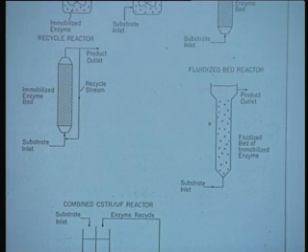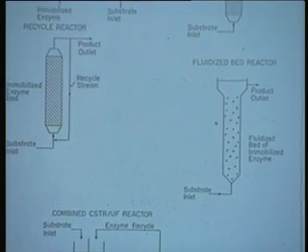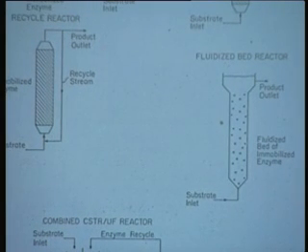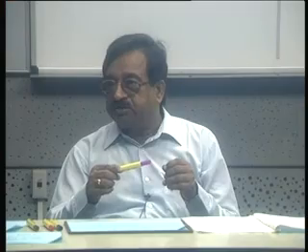It can act as a batch immobilized enzyme reactor, a packed bed with total recycle. The only constraint or assumption to be considered from the quantitative point of view, to treat it as a perfectly mixed batch reactor, is that the recycle time of the substrate must be very small compared to the total batch time.